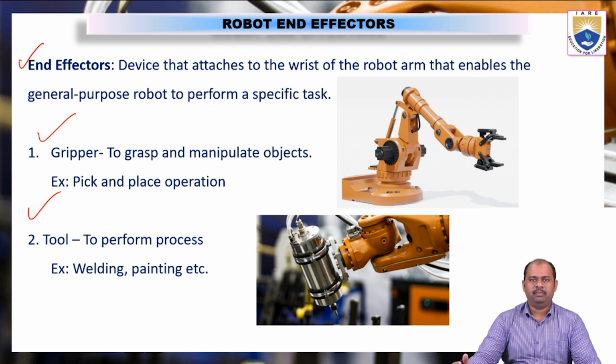If we want to pick and place an object using a robotic arm, the arm will move from the rest position to the position where the object is, pick the object from point A and move it to some point B. There it will release or place the object at point B, and again it returns to its original rest position. This entire movement of the object from one place to another is called manipulation. So the robotic arm is also called a manipulator.